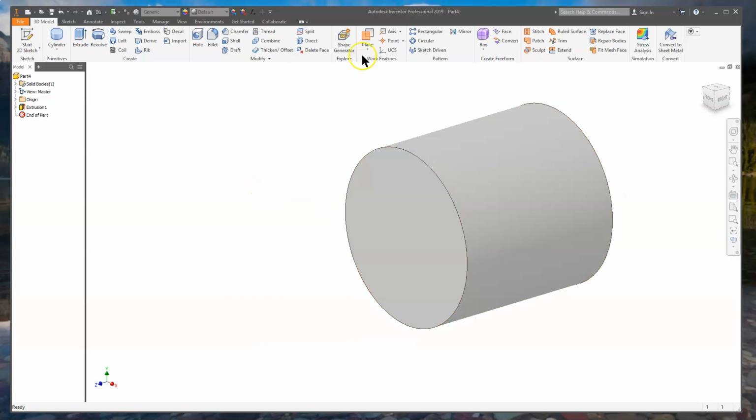Next thing I want to do is put a plane off the nose of it here. I'm going to start dragging out this direction, and I want that to be 0.625 away from the nose of that. No, I don't. I don't want a 0.625, right? I want it to be 0.25. There we go. That looks better. I click on OK. I've got my plane there.